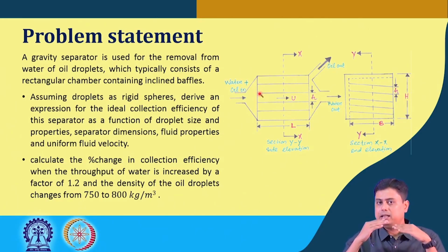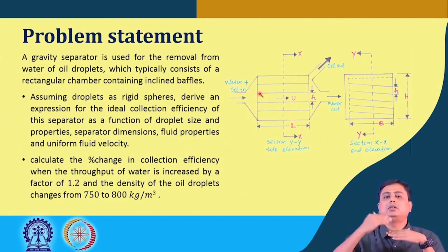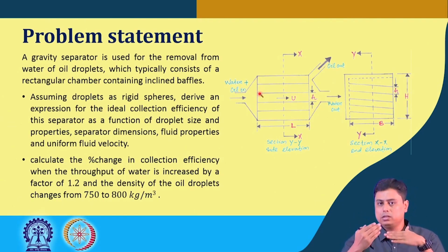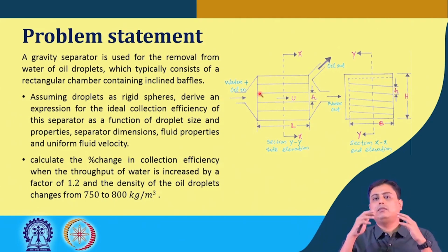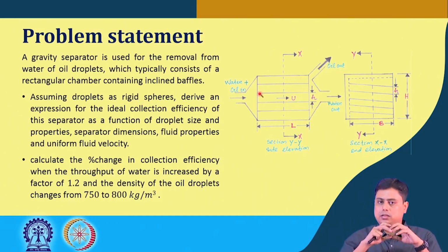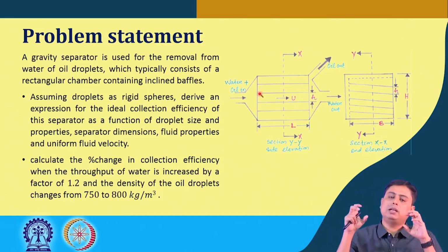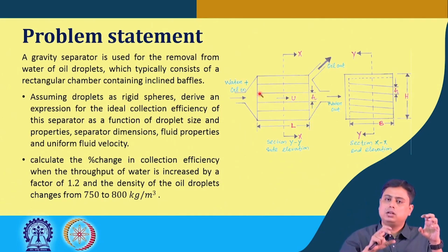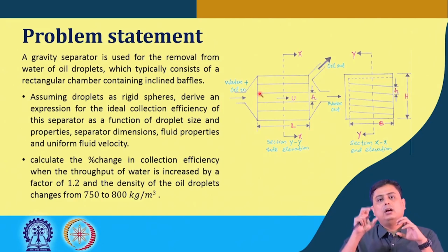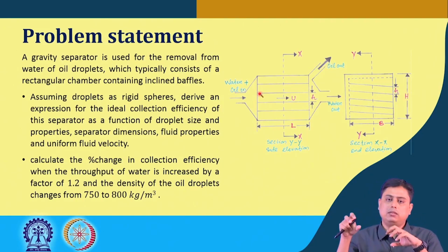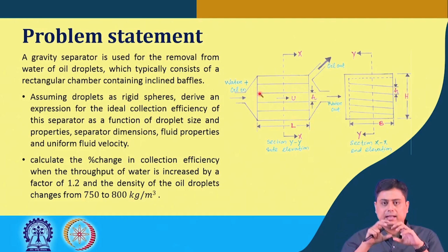So, the particles having, let us say, 50% of the terminal velocity of the minimum requirement, those 50% will be collected. The particles that have 25% of this minimum terminal velocity, again this minimum rise velocity depends on the droplet diameter in this case. So, the point is that depending on the percentage of the droplets that have those terminal velocities, exactly the same percentage will be collected.